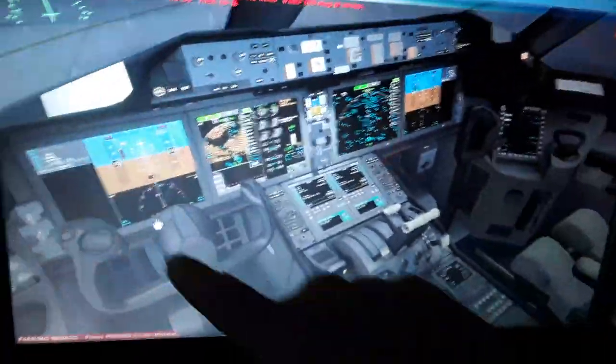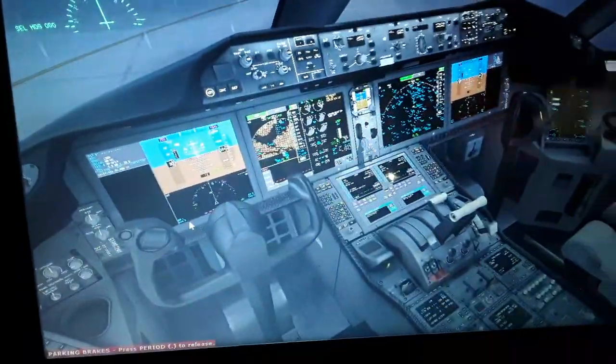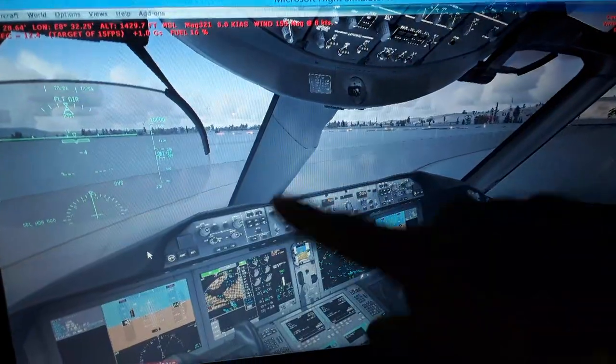So also you can see, besides the horizontal trim stabilizer here, we have the autopilot flight director system panel, which has the automatic trim. Since this is a fly-by-wire aircraft, it has the auto trim function when it's flying to trim and balance itself using the flight management computer inputs, so the autopilot flight director system panel, the auto throttle, and the flight control computers. So it will trim itself.